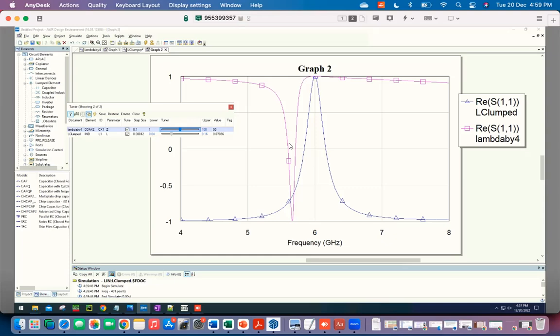In the sound case, it's interpreted as not a very hard boundary condition. So the actual length of the tube, in acoustics, looks effectively longer because the waves go beyond the end of the tube into the air a little bit and then reflect back. This is sort of like that, but in the electrical domain. The effective length of the resonator now looks longer.